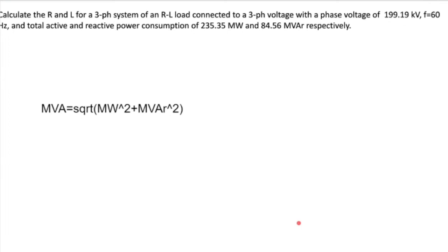But one thing you must always remember, everyone, is that power factor has nothing to do with per phase or three phase. Power factor is the same. If you calculate the power factor for one phase, it will be the same, given we are assuming that the resistance and inductance that we are considering in these two tutorials are the same for all three phases. They are not different. But if they are different, the power factor for each phase will be different as well. But that's a completely different scenario.